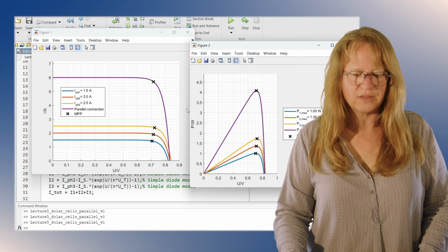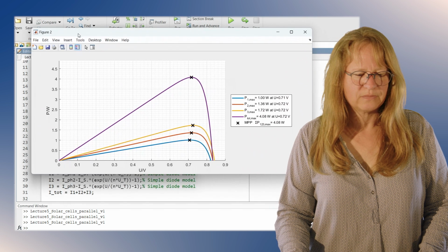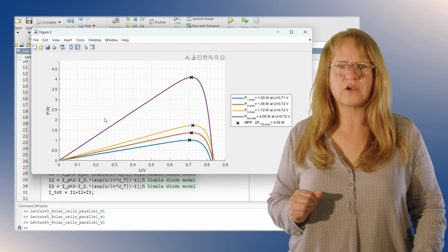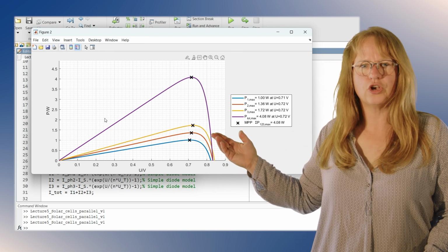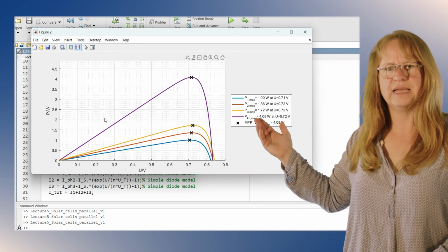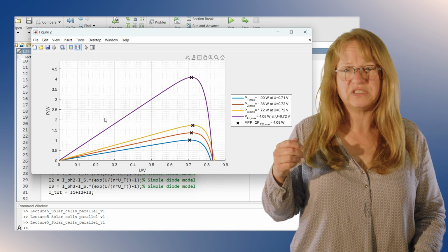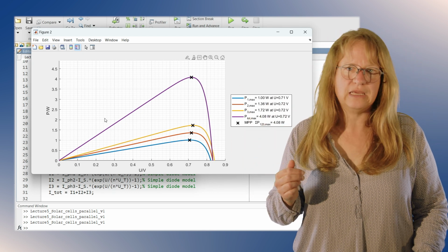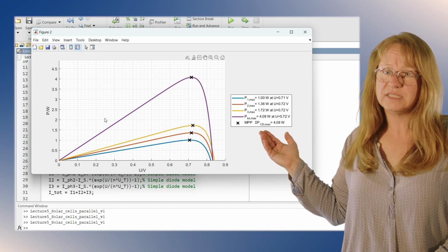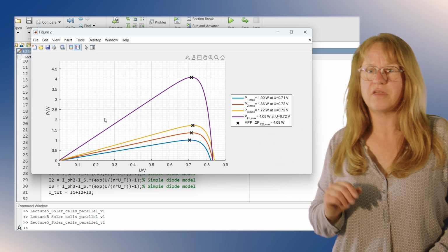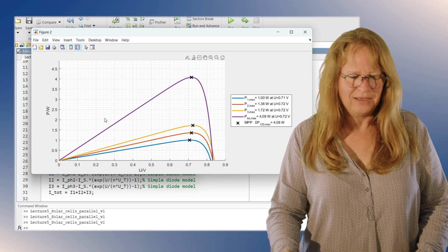And if we look at the power characteristics, so here we have the power characteristics now, and we can actually see that if they are close together, as shown here with just 0.5 amps difference respectively in the photocurrent, the maximum power is still the same as the sum of the 3 individual powers to the 2nd decimal place.